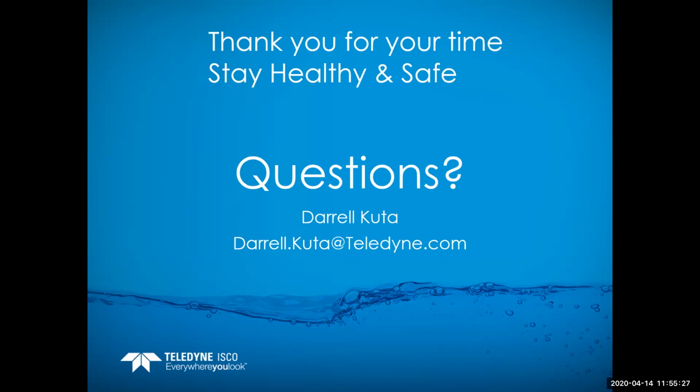What you'll see is the Doppler signal that's reported from the laser flow sensor. The Doppler signal is going to be lower, but as long as it's over 1,000, we're getting accurate velocity readings. The Doppler power, or Doppler signal, represents the amount of turbidity particles in the water. If you have dirtier water, the Doppler power is going to go higher. The cleaner the water, the lower the Doppler signal. It doesn't mean that it's better or worse, it just means that we have more or fewer particles in the water.